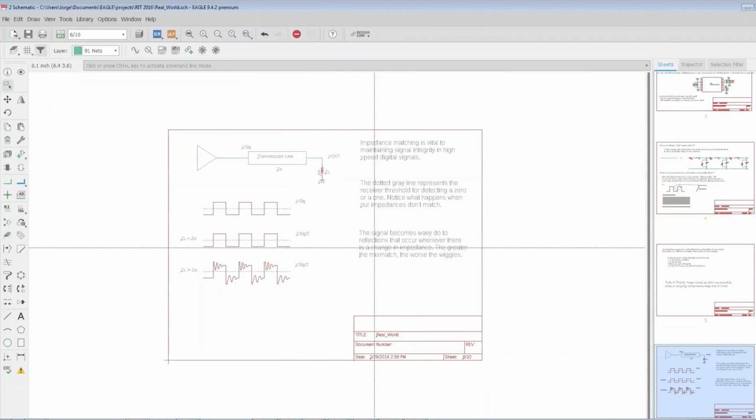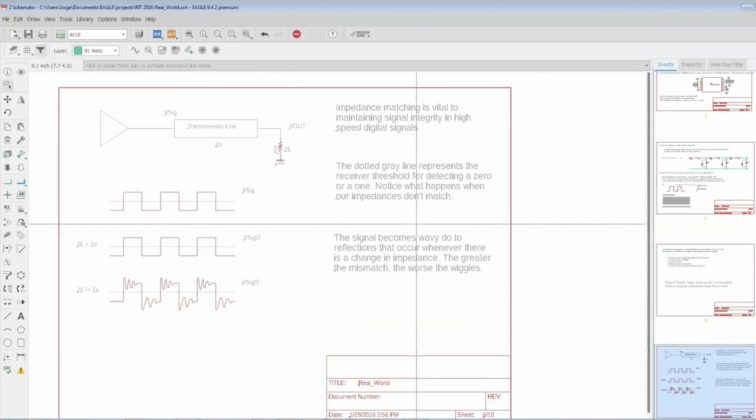Now, obviously, depending on the type of driver, the driver may have an impedance that it wants to match to, but your transmission line will have a different impedance, and in those cases, you'll have to do things to equalize them. But having it constant is going to make your life easier. Okay? So what are things that can create impedance discontinuities? If you have to alter widths halfway through your trace, that can create reflections.